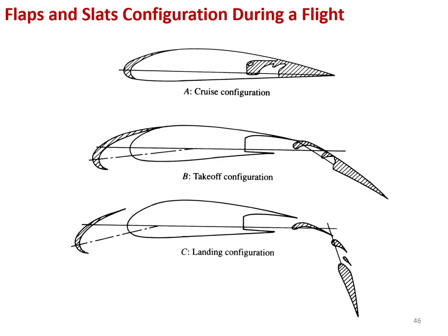So on a regular aircraft, we have different mechanisms at play. This is a regular airfoil on a common commercial airliner. The cruise configuration looks like a regular airfoil. During takeoff, when we need a lot of camber and a lot of lift at the same time, this is the configuration.